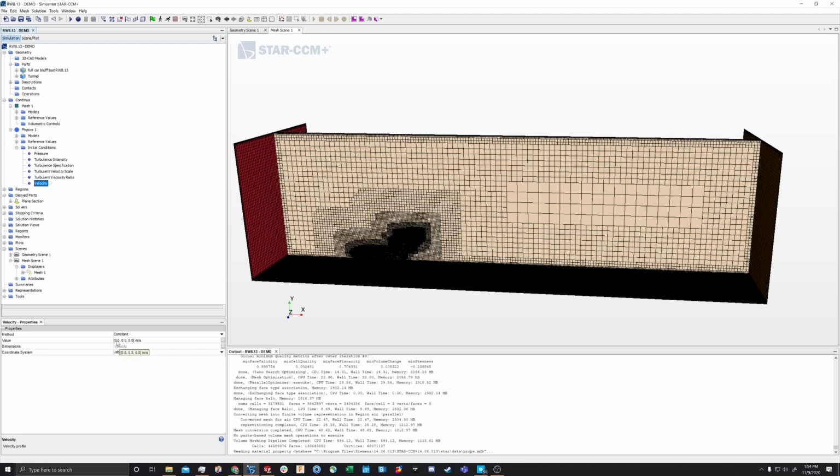And we're going to set that to 40 in this sim. And this is actually not necessary to set. The sim will run fine without an initial velocity. But it speeds up the time it takes to converge, because you're going to start with the air moving in the right direction from the beginning, whereas if you don't have that, it'll slowly get there through iterations. But yeah, we're going to set that to positive 40, not negative 40. That'd be a big problem.